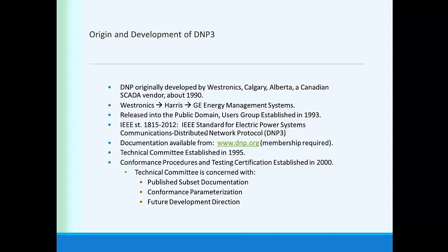It's well accepted. Its compatibility issues have been resolved. I don't want to give the impression that this is as far as technology can take us in terms of SCADA communications. I don't want to make this into a promotional thing for IEC 61850, but there are protocols available for SCADA communications that are being hammered out in pilot projects throughout the United States and through the utility industry worldwide, like 61850, that don't suffer from the limitations of 9600 baud, 32 and 16-bit integer communications.